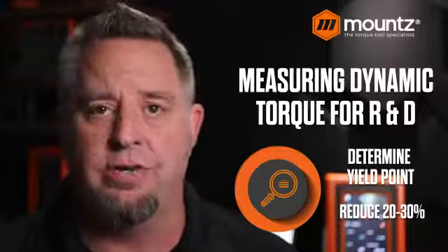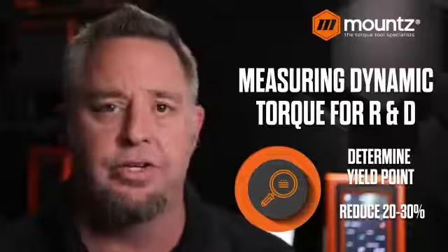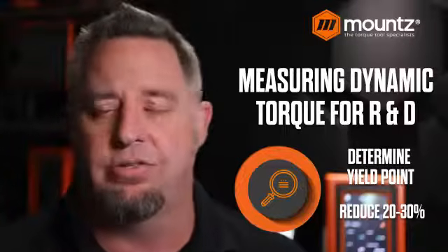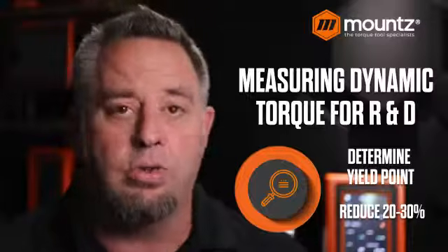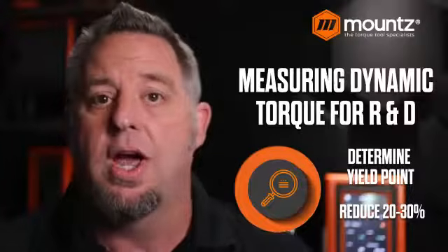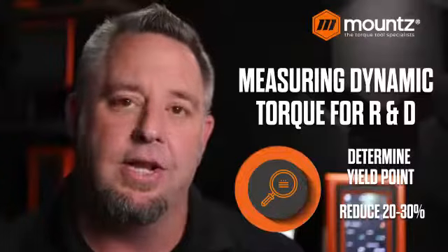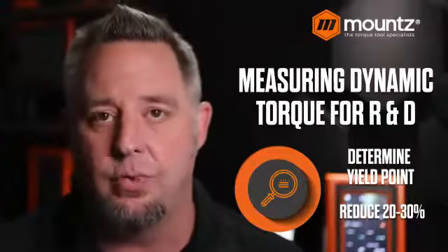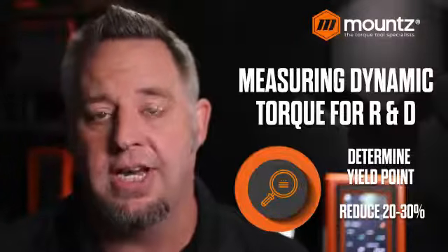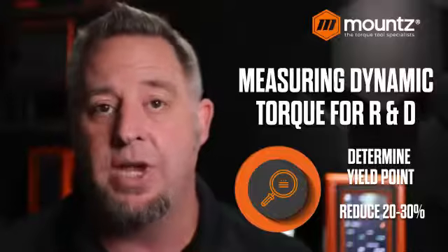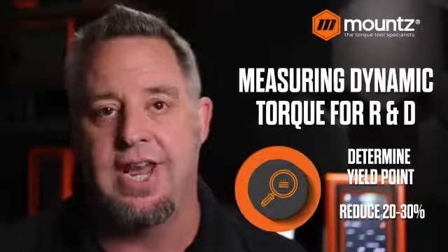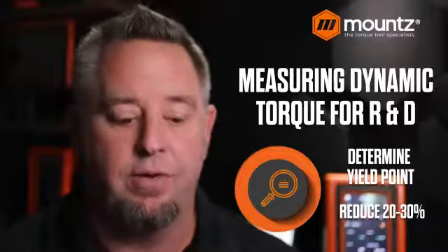If you're using torque equals the coefficient of friction times the nominal bolt diameter times the tensile force of the fastener. So there are things that we can look at if we're having issues with a particular fastener, and we can do some R&D to see if we need to adjust the torque setting. So a rotary style transducer is excellent for this type of process.